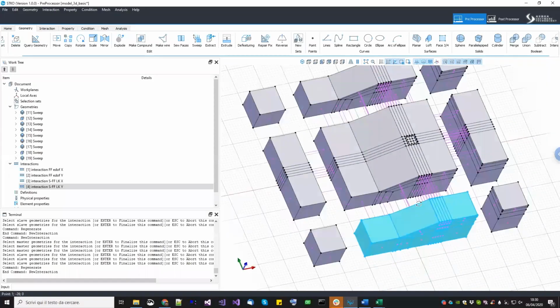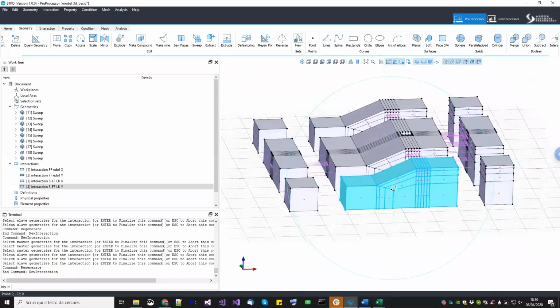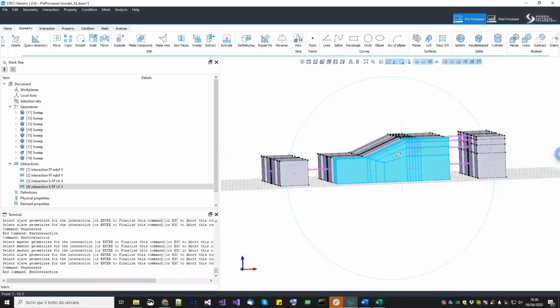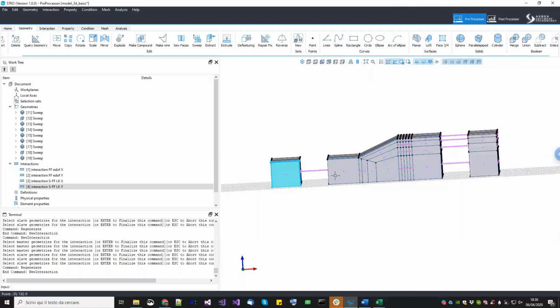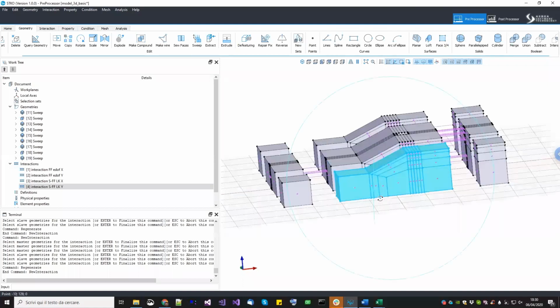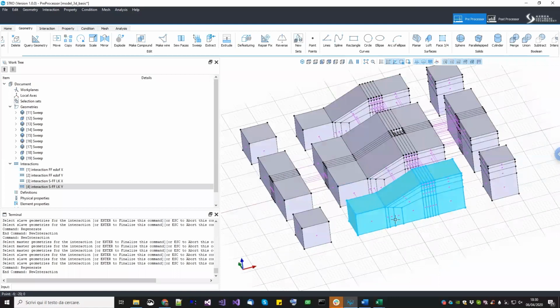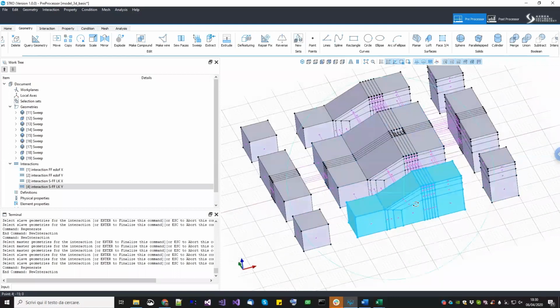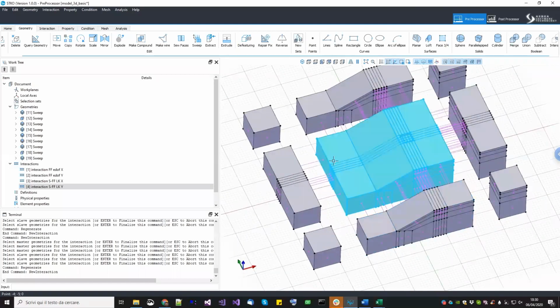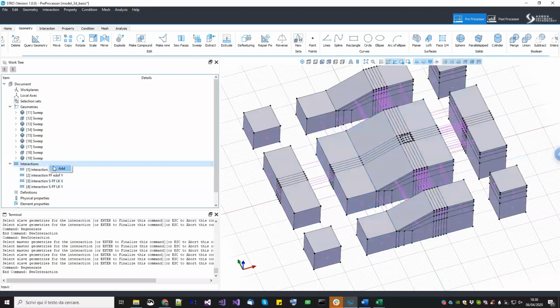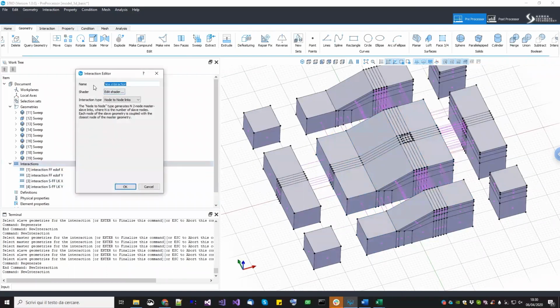Now, of course, if you look at the lateral free field column, this one by itself is like another 2D problem. So this one is like the interior soil domain now, and these two are its free field columns. So we need to create interactions between the lateral free field columns and their corners along the x and y direction as well. So we need two other interactions. So here, let's call it interaction free field Lysmer-Kuhlemeyer along the x direction.